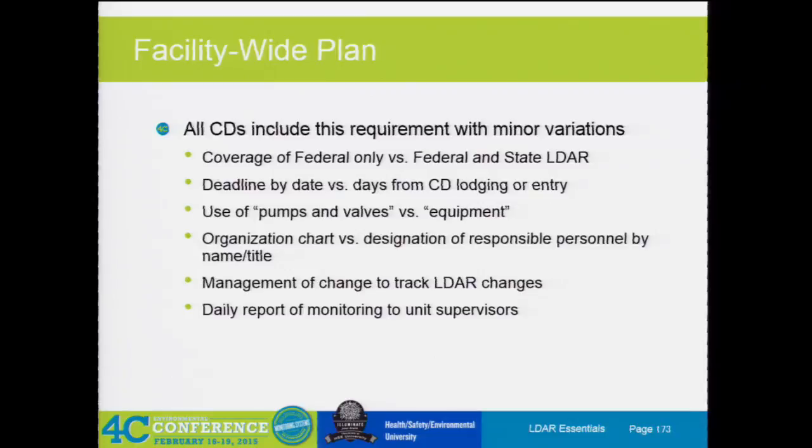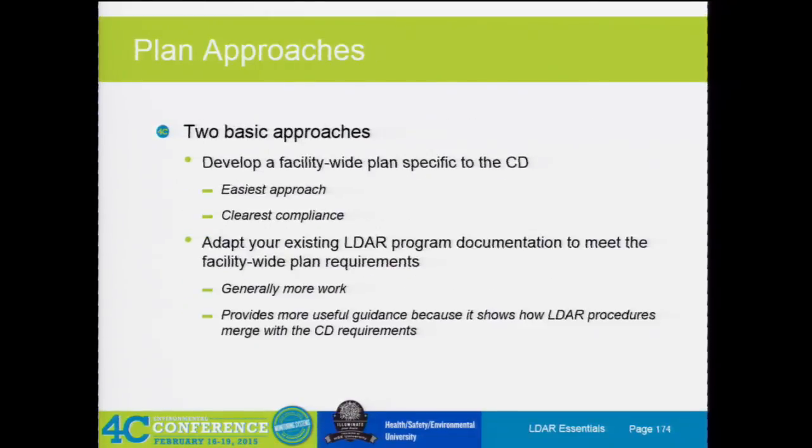One of the things you see usually in a written plan that may be something to look for is your unsafe to monitor reasons and all that stuff. Each component has to have a reason for being unsafe. You can't have a blanket reason for a set of stuff, so each one has to be itemized out, with the reason why it's unsafe and when you will go out and try to monitor it. Right.